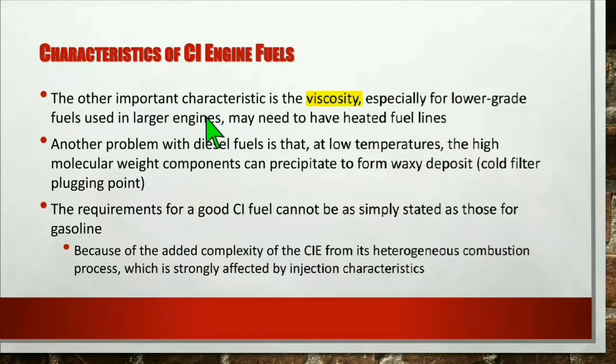The other important characteristic is the viscosity. Especially for lower grade fuels used in larger engines, heated fuel lines may be needed. Another problem with diesel fuels is that at low temperatures, the high molecular weight components can precipitate to form waxy deposit, called filter plugging point. The requirements for a good CI fuel cannot be as simply stated as those for gasoline because of the added complexity of the CI engine from its heterogeneous combustion process, which is strongly affected by injection characteristics.